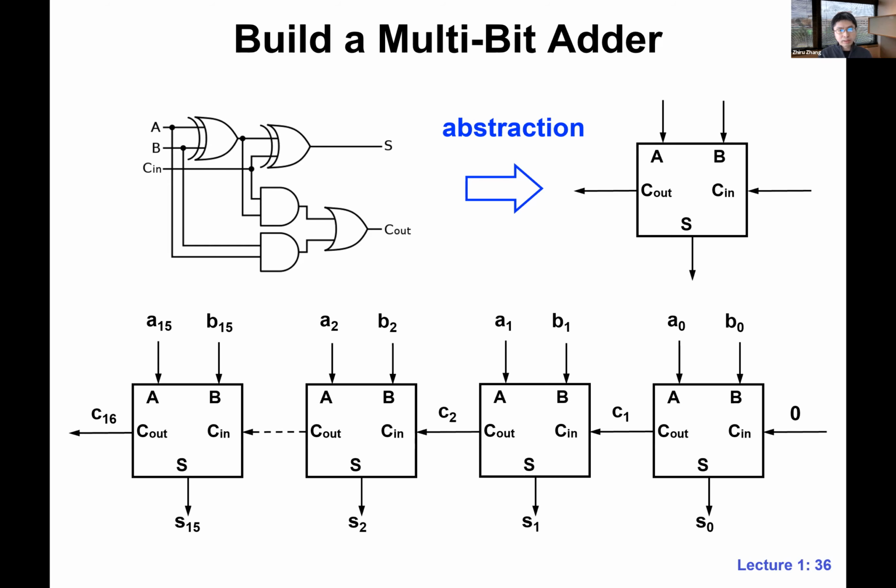And soon you will find out how we actually use this black box to build even more complex multi-bit adders. We just showed you how to do a 3-bit addition. We can actually do however many bits that we want. In this case, we are doing an addition for 16 bits. This is where we get the sum bits, and this is why we have something called carry. You can see that it's indeed being carried through many 1-bit adders.